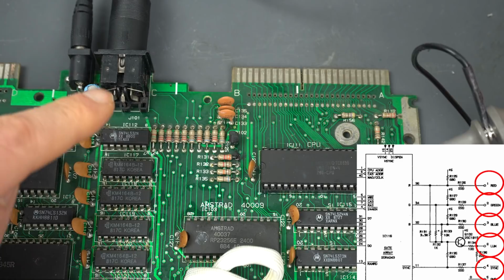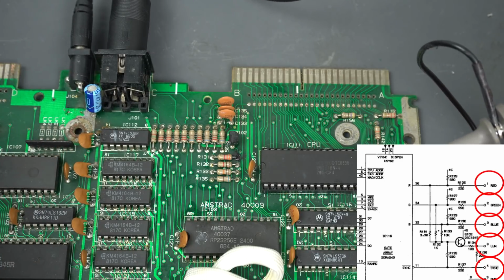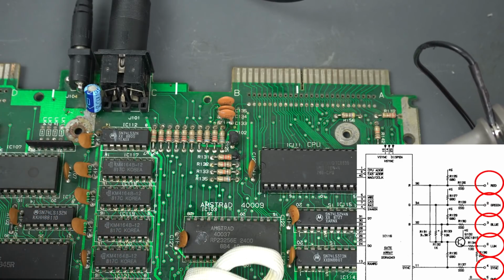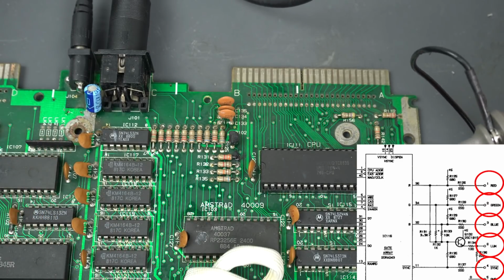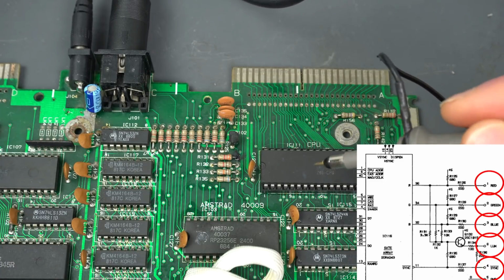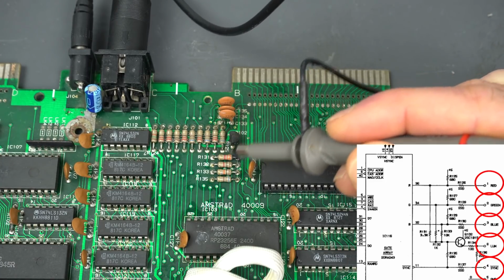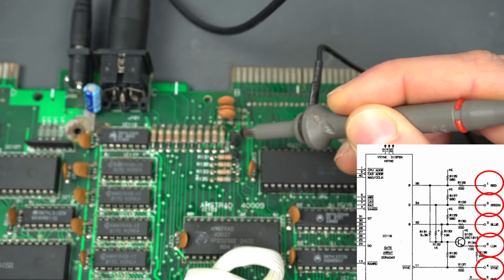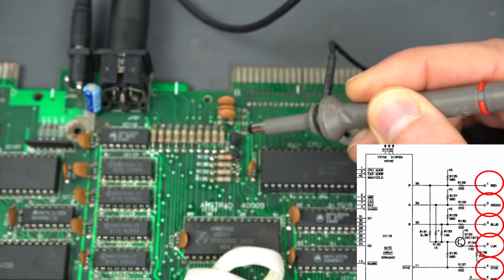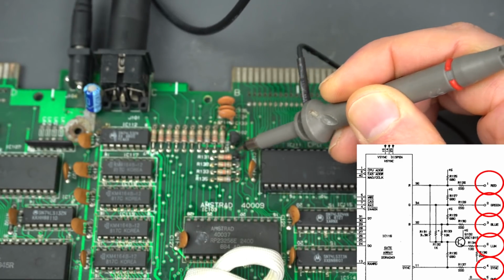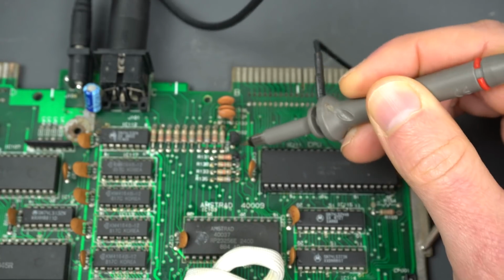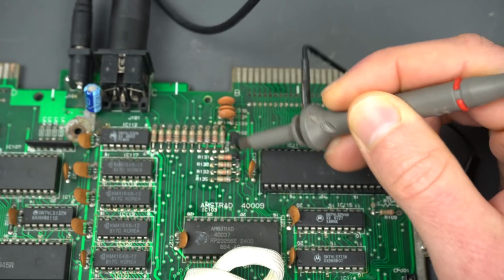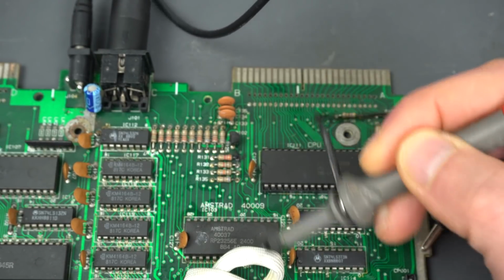And there's a luminance signal, which I believe combines the intensity of R, G, and B together, plus the sync signal, all of them together, into a luminance signal. And this transistor and those resistors are used to do that. So the transistors pretty much add the voltages together, and I believe the transistor just boosts that signal. So that looks really bad and really suspicious. This is definitely on the end of the video connector. So I cannot imagine this would be possibly related to the incorrect frequencies that we're seeing.